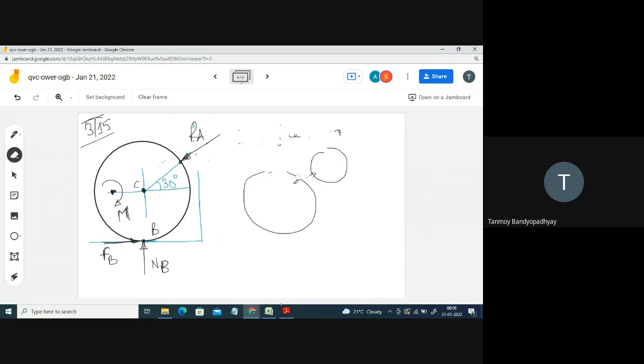So this RA I am supposed to find out. Okay? So how do we do it? Suggest to me. Arif has suggested we can apply the equilibrium equations. So either you can break this down into x and y component forces and write the equilibrium equations. It will be easy by equilibrium equation. Here you have to think about what unknowns you are having. I had a short discussion that you should be finding the moment at a certain point where the forces will be vanishing.